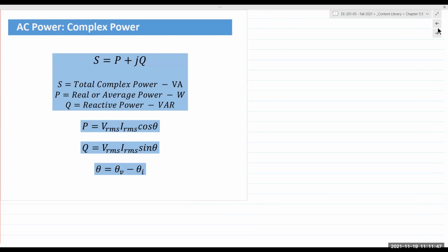So resistive circuit analysis, when you apply DC or when you apply AC, resistors behave exactly the same way, right? Energy is transferred, resistors absorb the energy and dissipate the excess energy as heat. Inductors and capacitors, however, are energy storage devices, and because they store energy, if you apply an AC alternating waveform to an inductor or capacitor, the energy will flow in one half cycle and it will flow out in the other half cycle, right? So it's constantly flowing in and out, in and out.